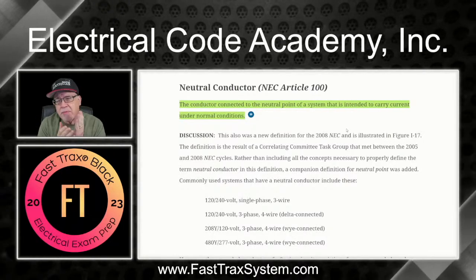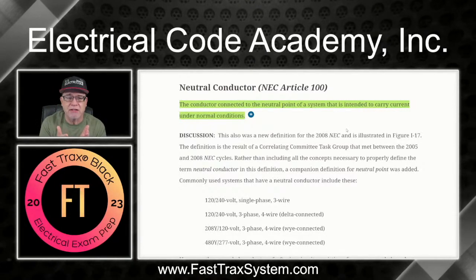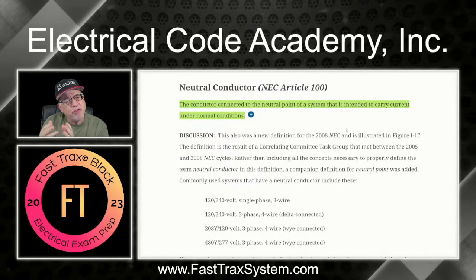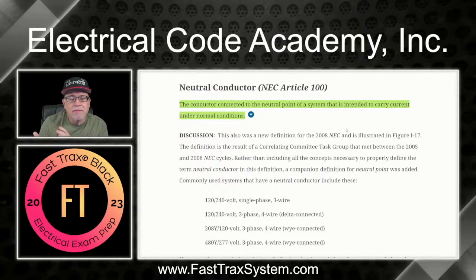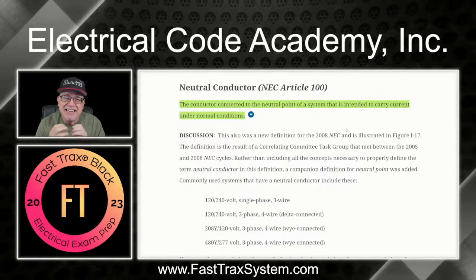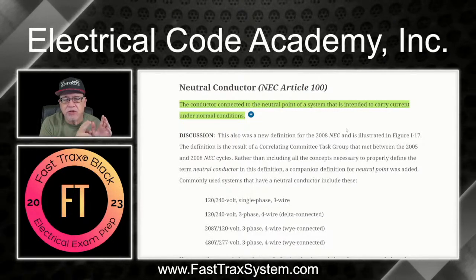Now, we understand the black conductor is a hot conductor. We call that an ungrounded conductor because it's not connected to ground in any way. And then you have the white conductor, which in a two-wire system like that, we refer to as a neutral. Now, since it comes from a grounded system, it is actually a grounded conductor.